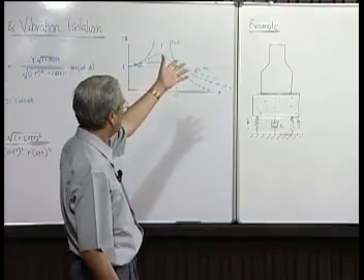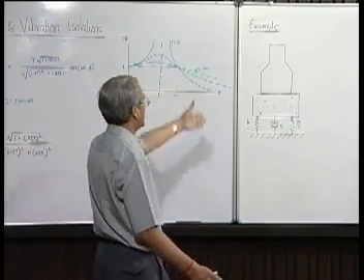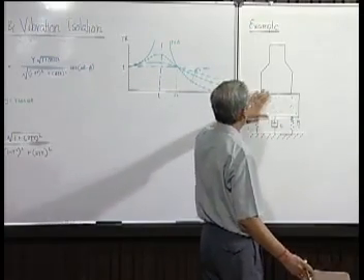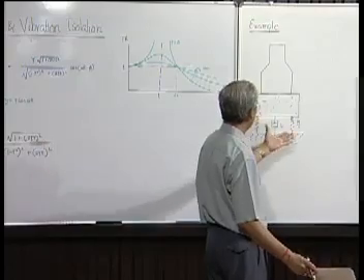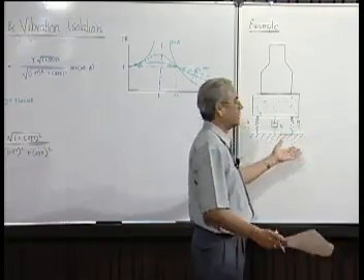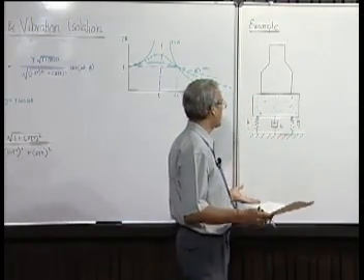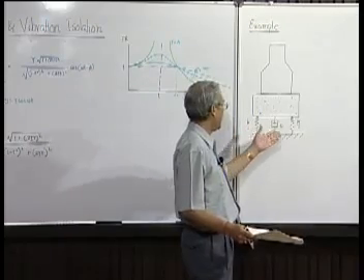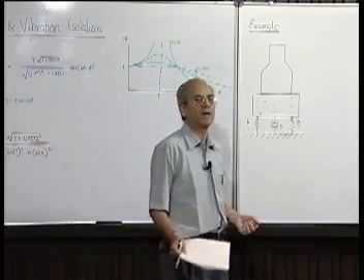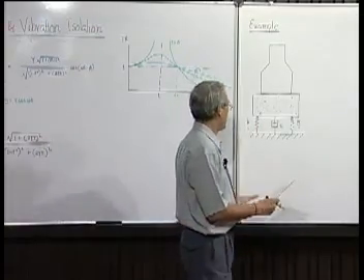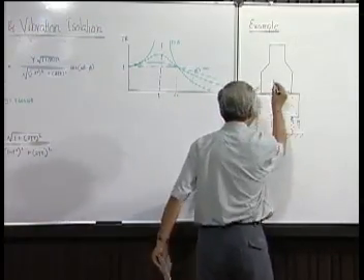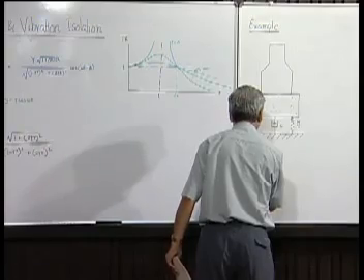So, this is an engine, a vertical engine supported on a concrete block. This concrete block again in turn is resting on a system of springs with total resultant stiffness of K and system of dashpots with total resultant damping coefficient C. The force which is unbalanced force which is developed.